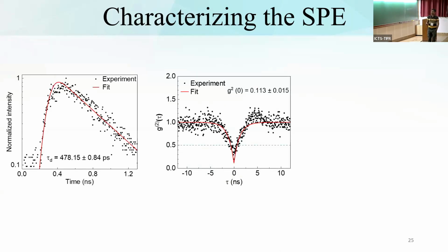Okay, so this is the lifetime number. It is about 500 picoseconds or so. This is much longer lived because it is not coming from the free exciton, it's from a confined exciton inside the defect. If you do everything right, and this is the radiative lifetime, it shows that ideally you should be able to go to something like 2 gigahertz. Of course, no one does, which tells us that this is really not the fully radiative lifetime. It does have a significant non-radiative component.